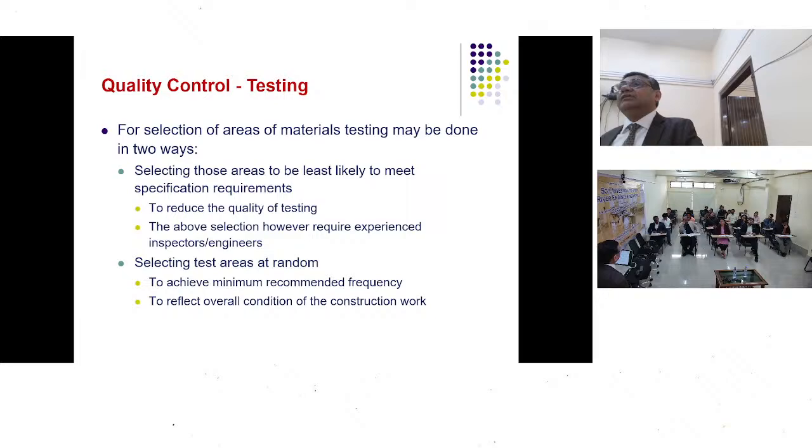Now you will say, okay, when the roller cannot compact, we have rammers, we have handheld devices for compaction. So those can be used. They have to be there. Also, when you are visiting, you will be able to understand. You may simply ask, "Achha, where is your handheld device?" And maybe the person who is in charge will be able to tell you the correct thing. They will tell you the fact. They will tell you, sir, it is kept aside, sir, we took it out the day before yesterday once, but it did not work. They will tell you the correct position. So that role you have to play.